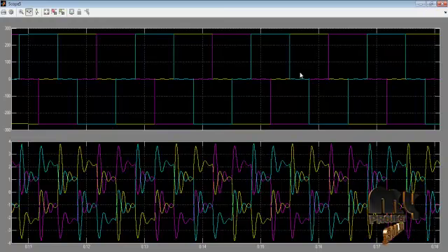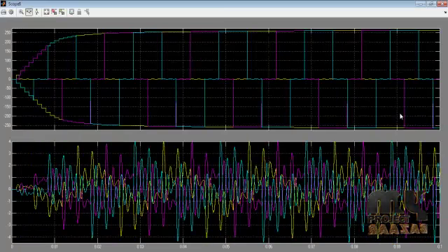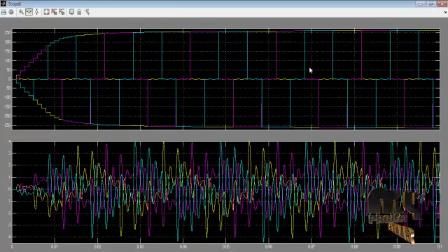This is the output AC voltage waveform, this is the output AC current waveform, and this is the staircase waveform. Before the filter, the inverter output is always a staircase, and next one is the unbalanced voltage and current waveform using unbalanced loads. So this is the output voltage waveform, this is the current waveform. The output voltage is around 250 volt, and the output current around 3 amps.